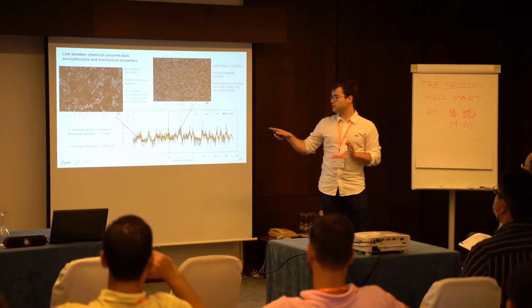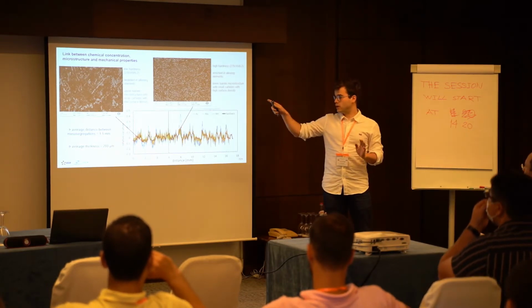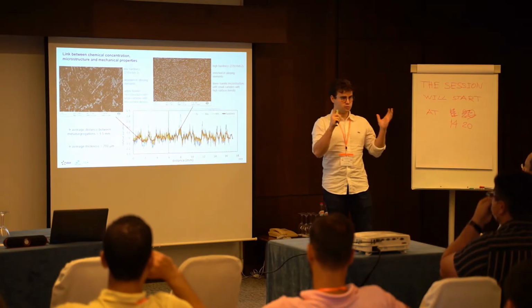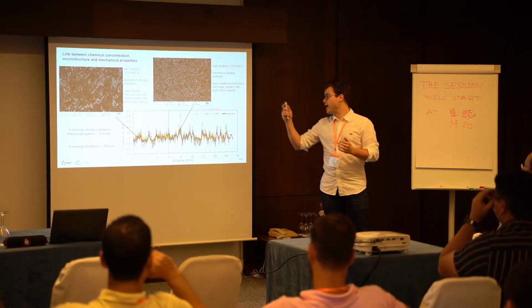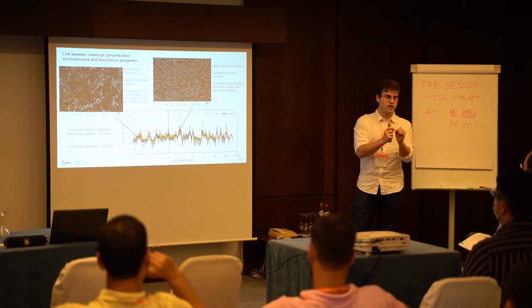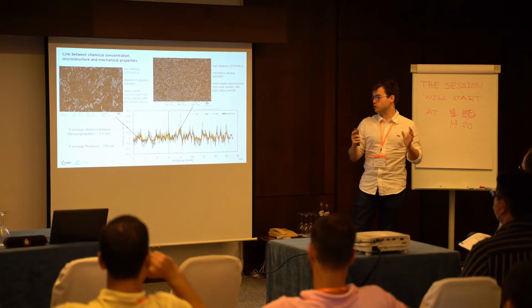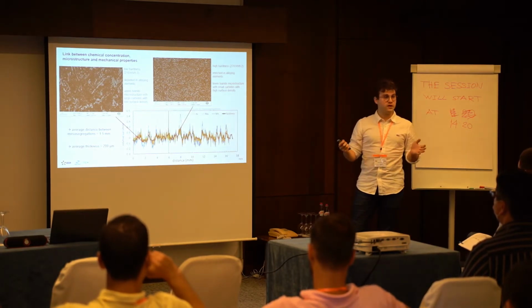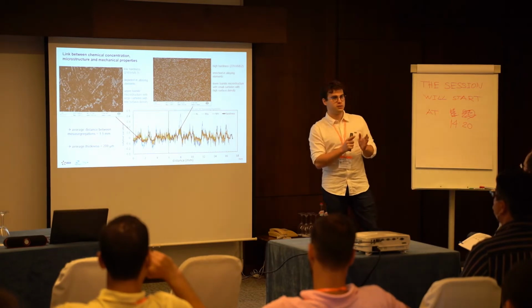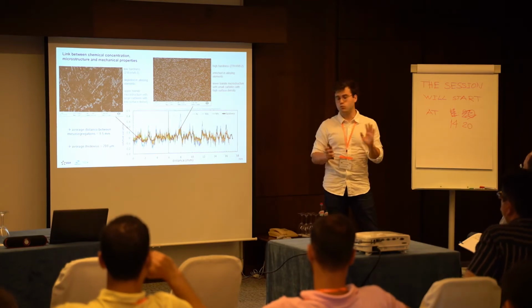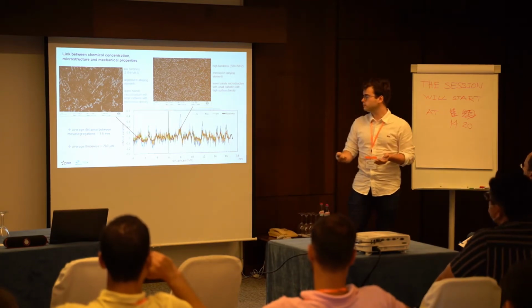Basically, in the depleted metal, there are big carbides with low surface density, and inside the meso-segregation you have smaller carbides and a much higher surface density. We also showed that the average thickness of meso-segregation is around 200 micrometers, and the distance between the segregations is more or less 1.5 millimeters.